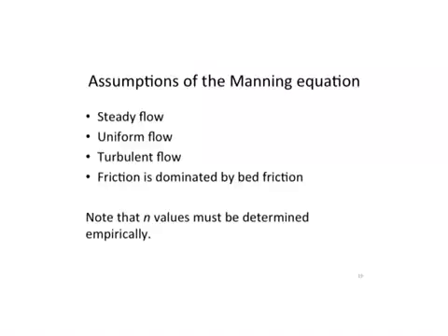Now, the Manning equation makes a few assumptions. It assumes, first of all, that the flow is steady and uniform. Remember, this uniform assumption gives us S_F equals S. It also assumes that the flow is turbulent and that the friction is dominated by the bed rather than things sticking up from the bottom of the river, such as plants. The Manning's n values are usually determined empirically. There are actually tables in engineering textbooks that will let you know what the value of Manning's n is for a given stream.